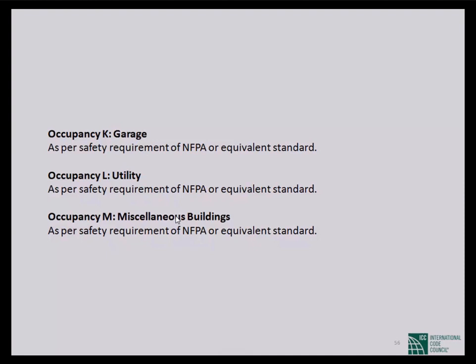If you would like to design, now in Bangladesh, there is a metro service going on. If you would like to design a metro station or anything, you have to consult NFPA 130. Just for example, I am talking about that. So this type of special miscellaneous building should be consulted with a special arrangement and special provision of the NFPA, nothing is said in the BNBC.